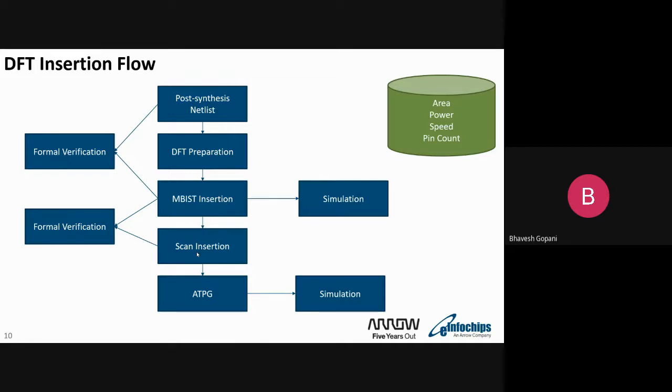So most of the area overhead is by the MBIST. And in one of my small chips, my last chip, the area overhead due to memory BIST is 4 to 5%, and around 1.5 to 2% for the scan only, of full chip area, I can say. But it was a small chip. When it's a bigger chip, the number is around 10% or something, I guess. 10 to 20, 15 also is possible, but I think not more than that.